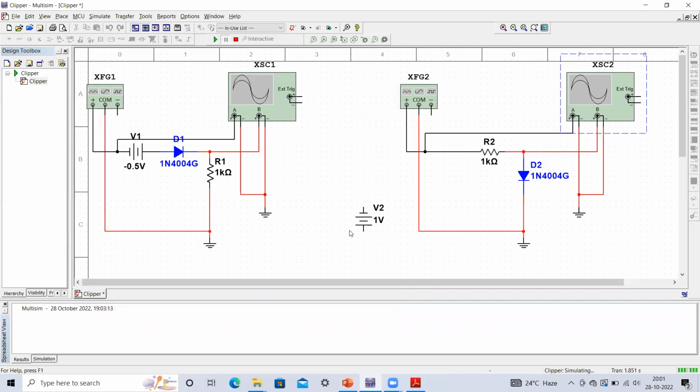Again, if you add a DC component, let us suppose we are adding a DC power supply, you can please do the analysis by writing the KVL expression, and then use the piecewise linear model or simplified model of the diode. Replace it with its cut-in voltage whenever it is forward biased, and then try to identify at what percent it is going to be forward bias and at what percent reverse bias. This way you can do the analysis.